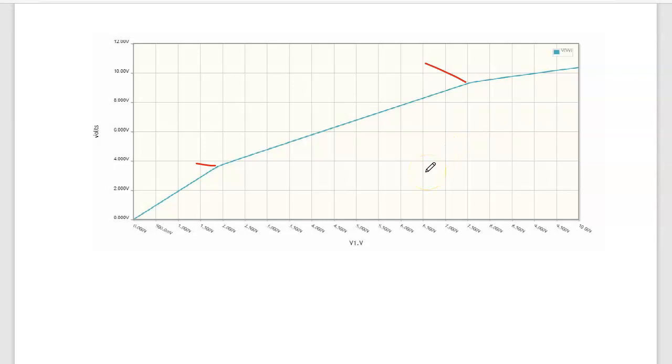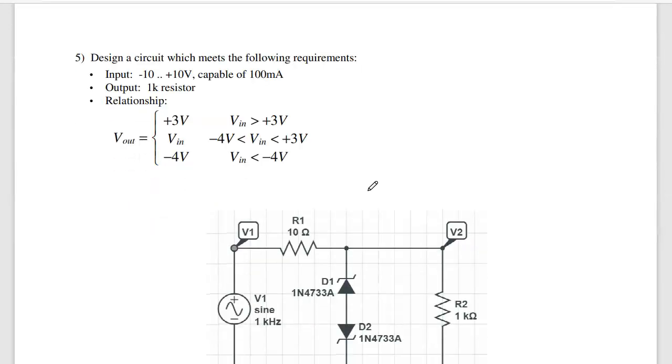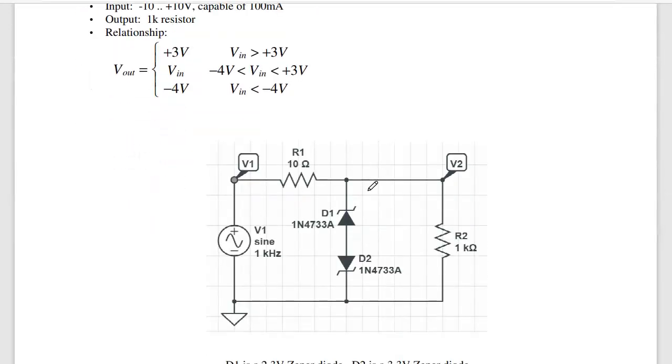So that's a clipper circuit. The neat thing about that is I can implement any function as long as it's monotonically increasing, meaning going up, using an op-amp circuit. I'm not exactly sure how this is useful, but you can do it. Today what I would use is just a microprocessor and calculate what you want Y to be. But you don't have to use a microprocessor. You could use diodes. For example, we got to the moon in the 60s. That was before microcontrollers. We were able to do it. We could compute functions using hardware circuits like that.